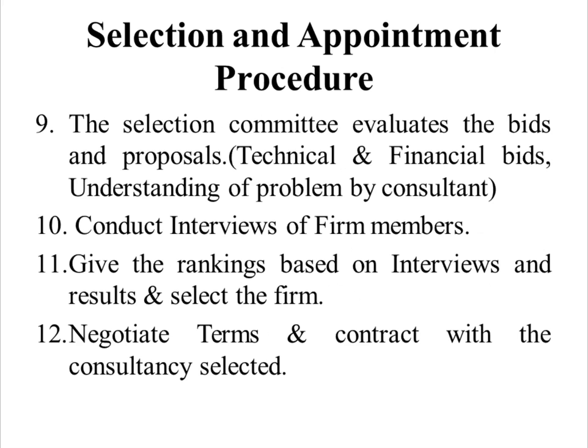The next step for selection and appointment procedure is the selection committee evaluates the bids and proposals, that is technical and financial bids, understanding of the problem by the consultant. Then the selection committee conducts the interviews of the firm members. Next they give the rankings based on their interviews and results and select a firm. And finally, the negotiation of the terms and contract with the selected consultancy is done.